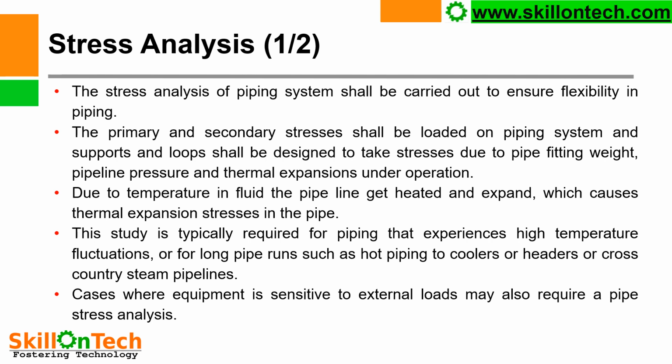This study is typically required for piping that experiences high temperature fluctuations, for long pipe runs such as hot piping to coolers or headers, or cross-country steam pipelines. In cross-country pipelines, the pipelines are in a very long length. It may be in kilometers. So in cross-country pipelines, we cannot always go and survey the complete pipeline.